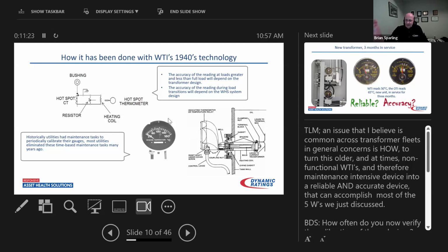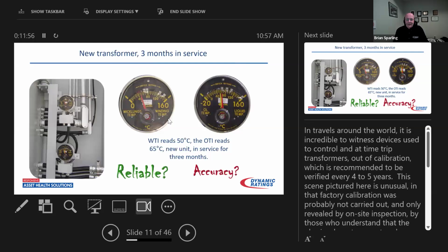What it does is that, and you can see the cutaway there of what it looks like installed on the transformer. You have a dry well and a tube that goes inside. The bulb is basically a bulb to control the expansion and contraction of a fluid that drives the indicator needle in there. So once this is properly calibrated at the factory, before the transformer leaves the factory, it's a simulation of the winding hottest spot winding temperature in the transformer. That's what it's meant to do.